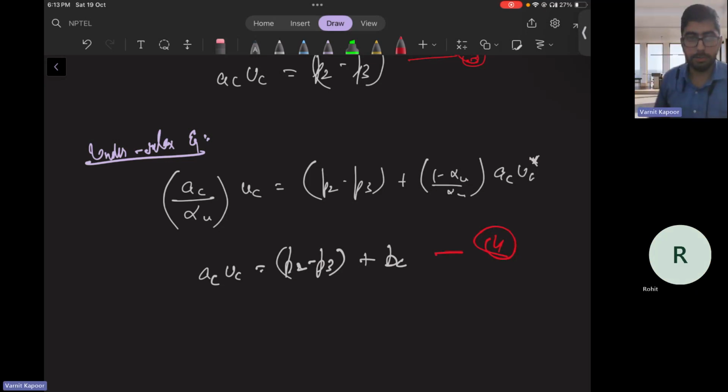We need to find the pressure instead of making an approximation. What do we do? We take an approach where we discretize the governing equation on a half cell.